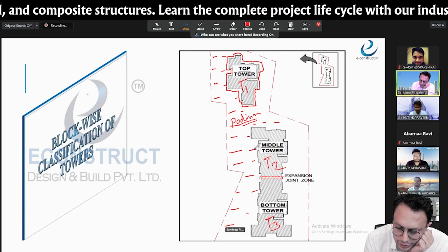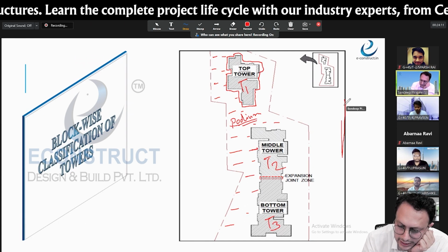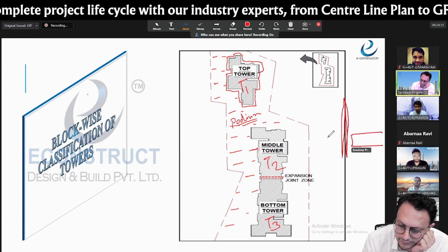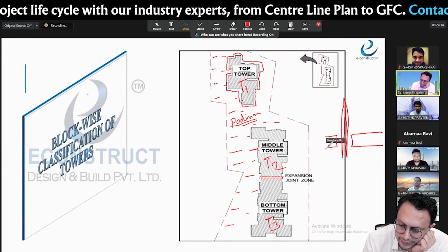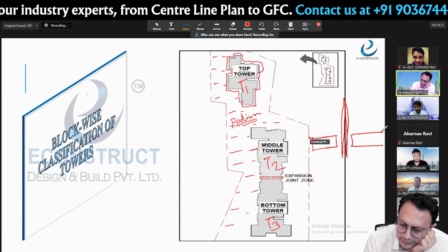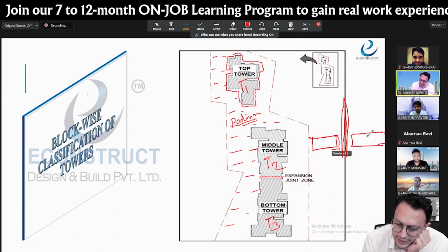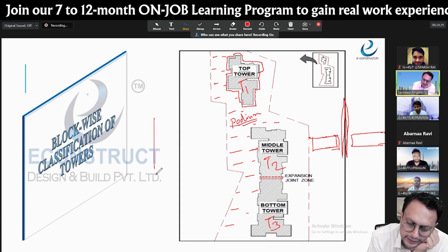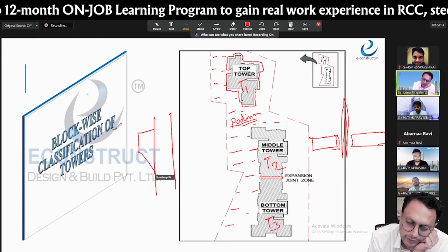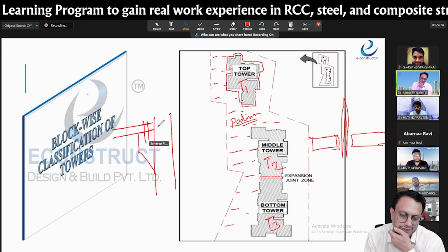I would like to just show you one. Let's say for example, if this is the line of the expansion joint, this is the tower column, and you will have here a podium column. This is the podium column. You can have this as a facility, or there is another option where you can have a column, and on that you will have a corbel, on which another slab will be rested, and here there are the joints.